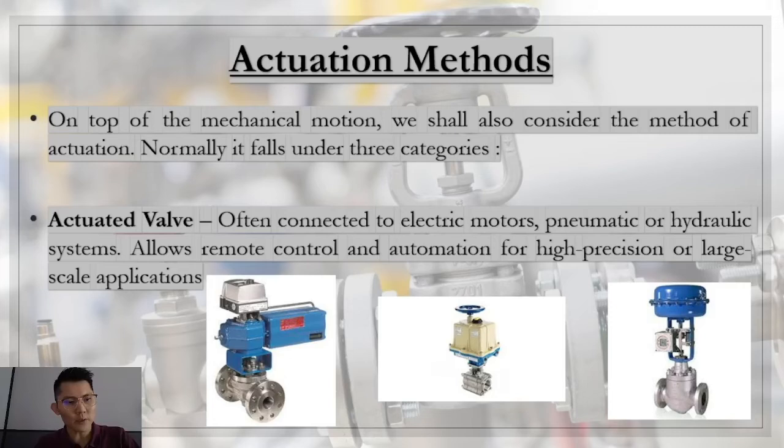Yes. Okay, so first, attending to Wai Chong, the actuator design depends on the valve construction, the valve materials, or what we call the valve specification. The design, I would say, is according to the sizing calculation. The actuator also comes in different constructions, for example rack and pinion, Scotch yoke, piston type, and diaphragm piston type. Different types of construction will have a different torque output curve.